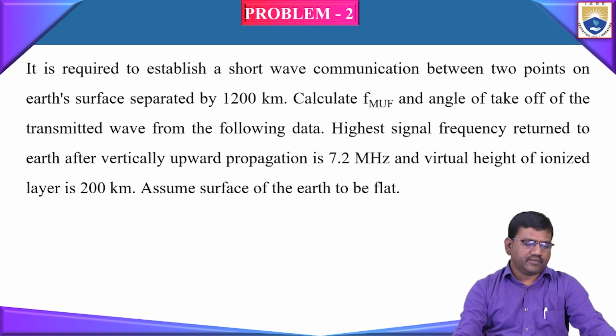Now let us do the second problem. It is required to establish a shortwave communication between 2 points on Earth's surface separated by 1200 kilometers. Calculate the MUF, maximum usable frequency, and angle of takeoff of the transmitted wave from the following data. The highest signal frequency returned to the Earth after vertically upward propagation is 7.2 MHz, and the virtual height of the ionosphere layer is 200 kilometers. Assume the surface of the Earth to be flat.